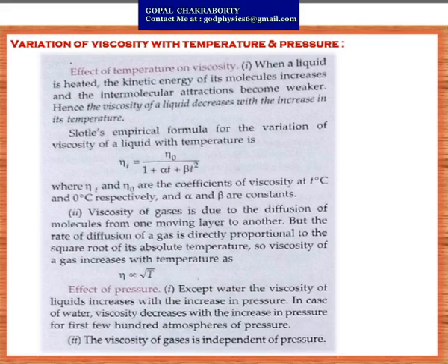Now the effect of pressure. Except for water, the viscosity of a liquid increases with increase in pressure. In the case of water, viscosity decreases with the increase in pressure for the first few hundred atmospheres of pressure. Secondly, the viscosity of gases is independent of pressure.